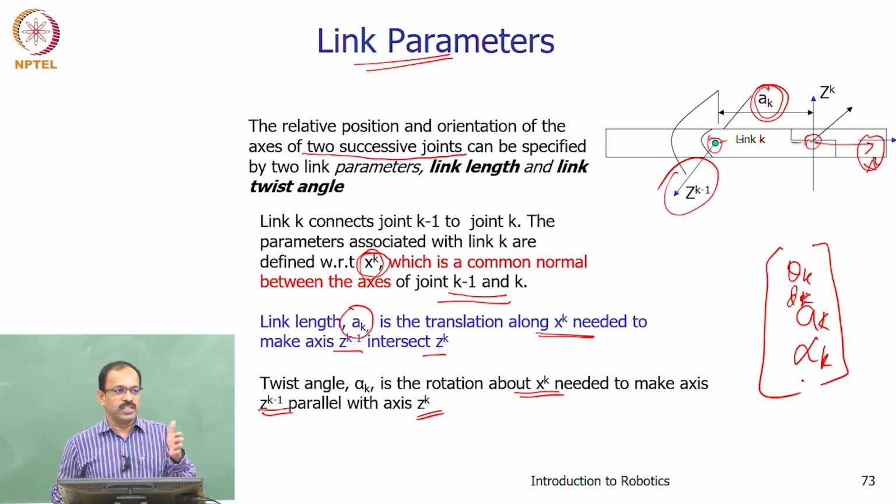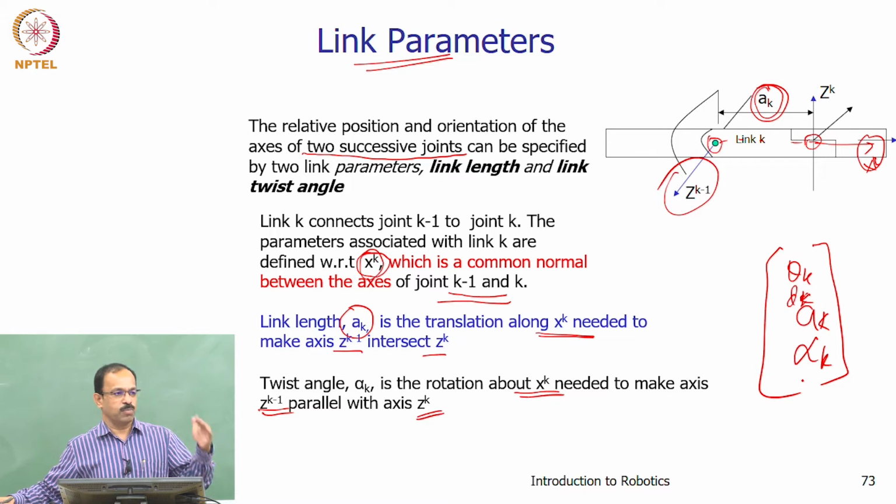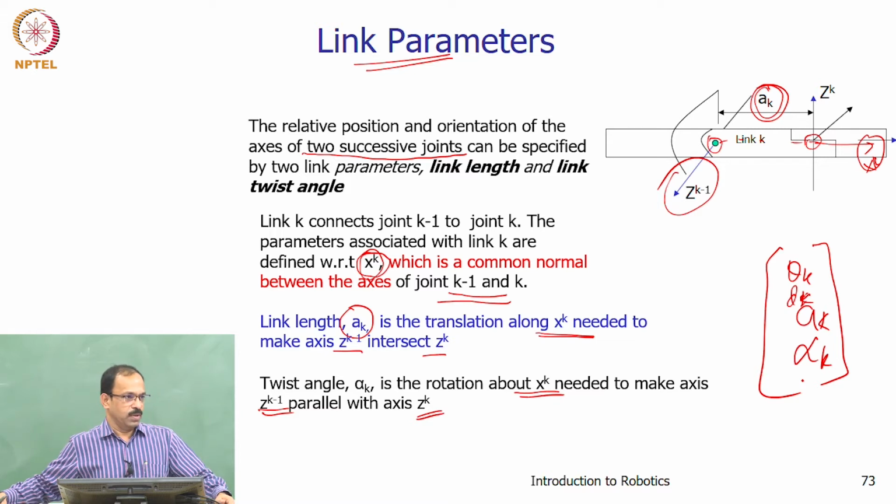You can still do it theoretically, but your kinematics will be much more complex, because depending on alpha, you may not be getting the xy another degree of freedom completely. Because then you have one joint like this and one joint like this actually moving into a different plane. But if you make it 60, you won't be able to completely move to that different plane. So you may not be getting a full motion in that case. So normally alpha will be 90 or multiples of 90.